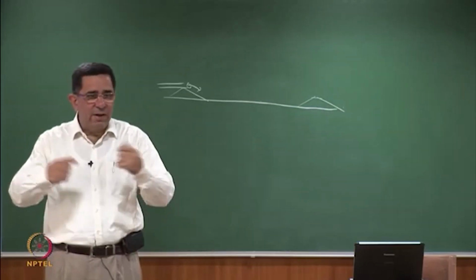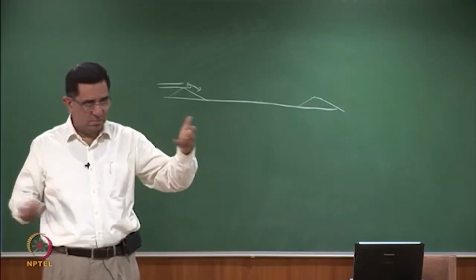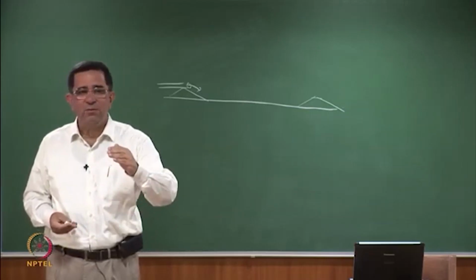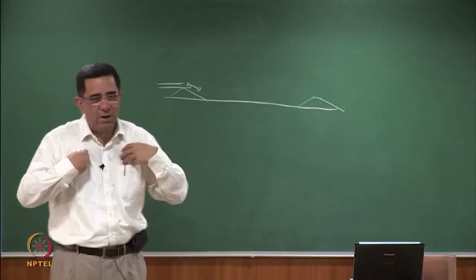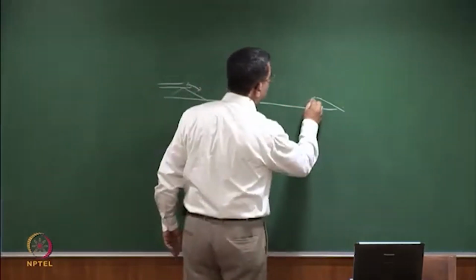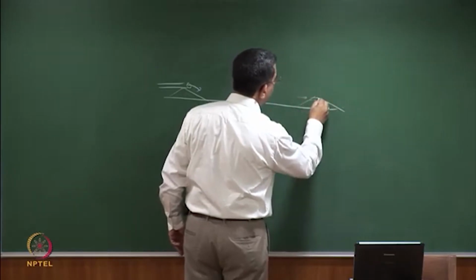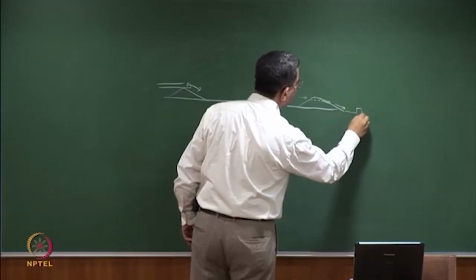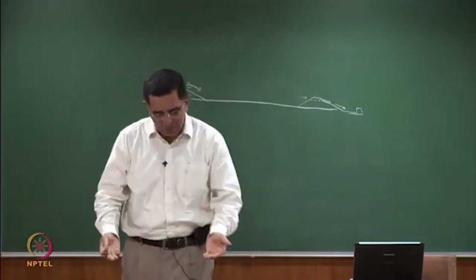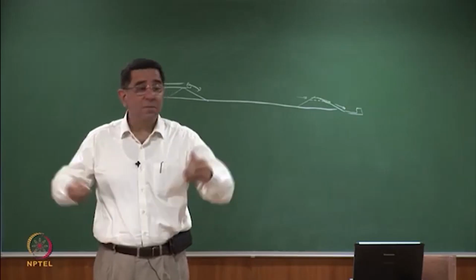We can have a spillway, we can have a trench, we can have something to pump it out. These are some of the options. But we don't want the phreatic line to be high. See, one of the ways I can say is, let me put an overflow weir here. Just a thought. Let me put an overflow weir here, like a spillway, and when the water level comes, I can have an energy dissipator, and I'll allow the water to overflow. But that means I'm going to allow the water to reach the crest of the spillway, right? That means I'm increasing the water level.